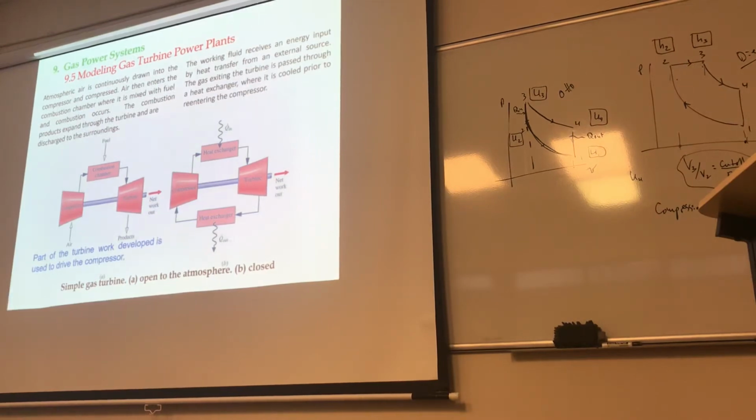We're going to say that, hey, we're compressing something, right? And then instead of talking about combustion, again, we ignore combustion. What do we say? We're just adding heat. Okay? That's the same thing, right? That's the goal of the combustion. And then after you go to the turbine, what is the difference between these two? I mean, granted, obviously, you need fresh air, right?